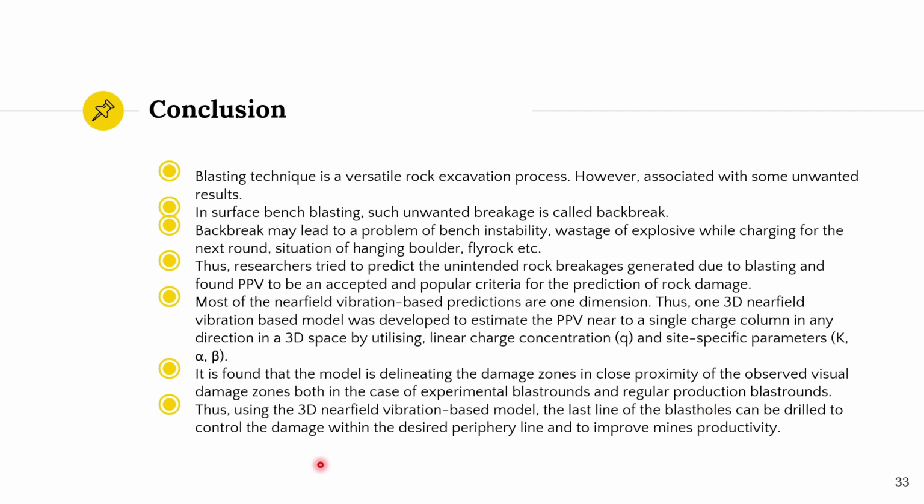Thus, using the 3D near-field vibration-based model, the last line of the blastholes can be drilled to control the damage within the desired periphery line and to improve the mine's productivity.